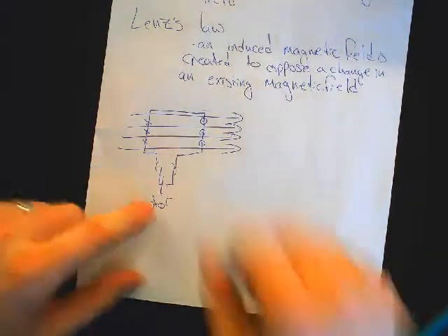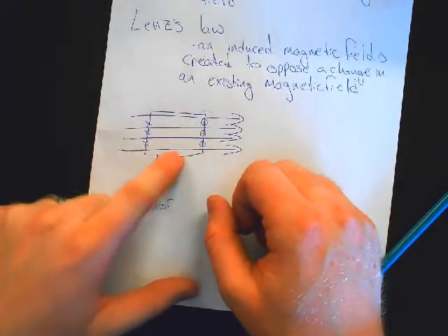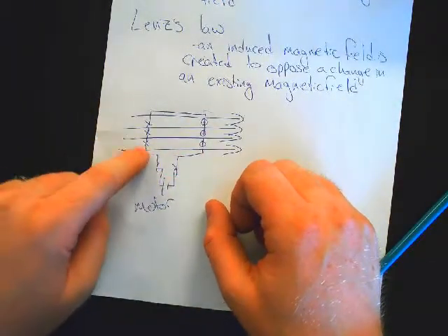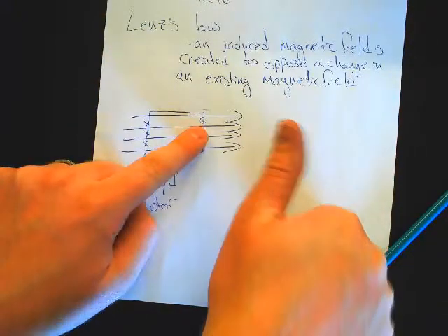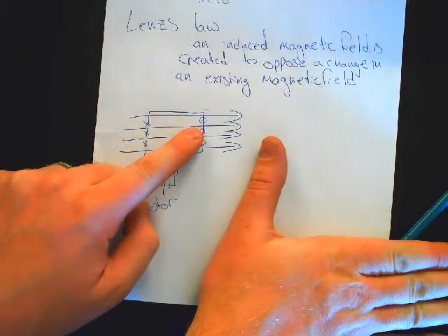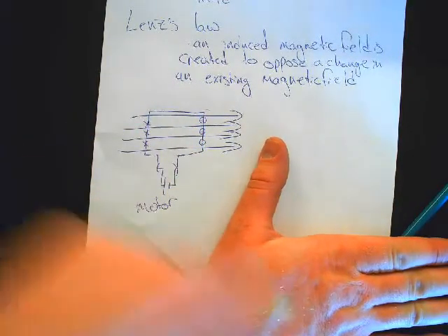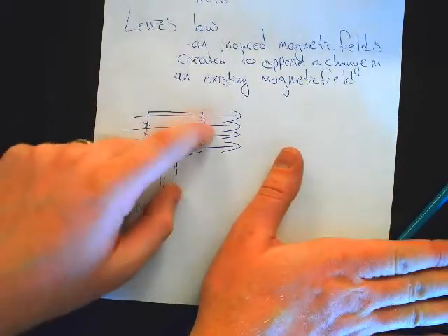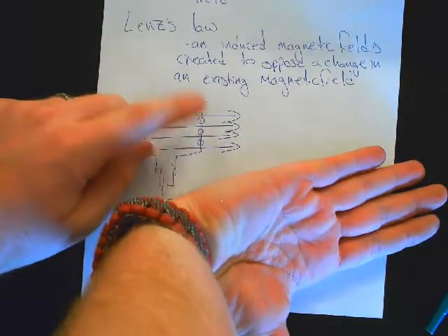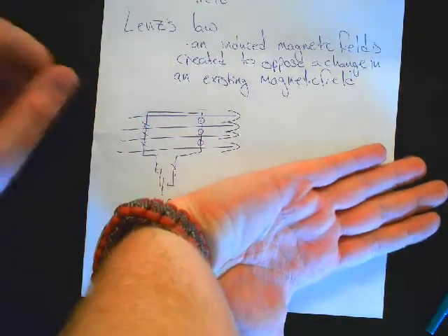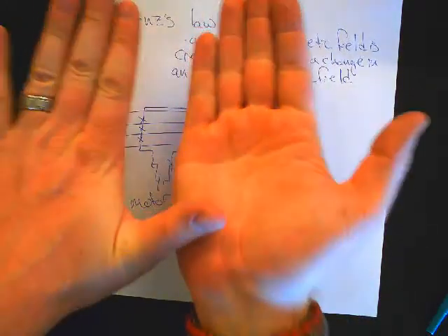Sure. So I've got the positive side of my battery, therefore I know current's going out this way. Current in this segment's going up. Current in that segment's going up. Magnetic field is going that way. Magnetic field is going that way. And therefore the force is being pushed down into the page. Okay? On this side, exact opposite. Magnetic field still going in the same direction. Current's now coming down, but my palm is now facing up out of the page. So it gets pushed up. And I get this thing to spin like this.